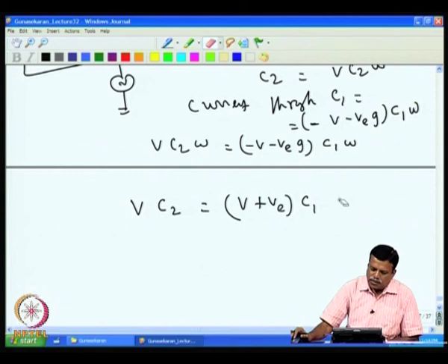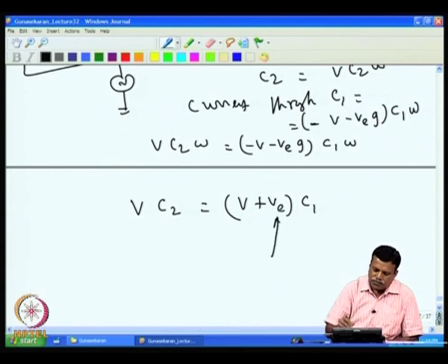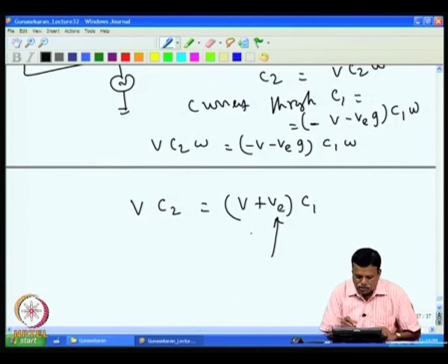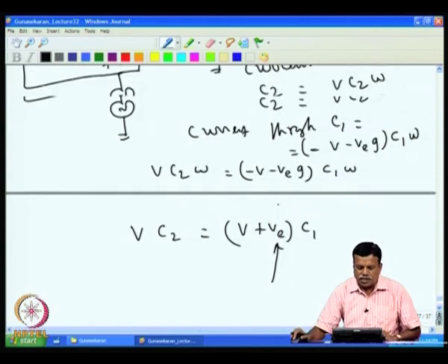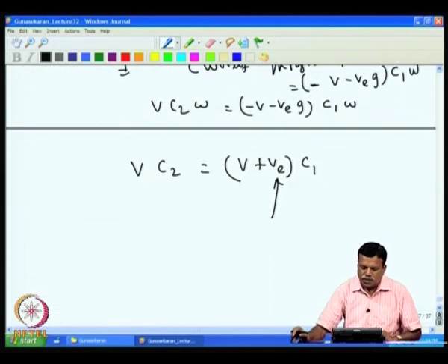So, it has done the balancing technique of the ratio transformer, because if you see, we are adding now VE. If C2 is large, automatically VE is plus, if C2 is small, then VE is minus. VE polarity is getting adjusted automatically, because the output voltage is inverted here. So, the bridge automatically balances out.